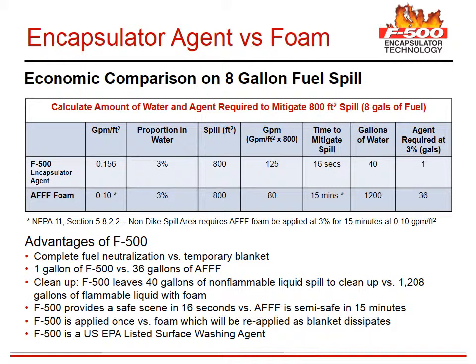At 3%, the foam will use 1,200 gallons of water. The F500 will only use 40 gallons of water. Per NFPA 11, there will be 36 gallons of foam used compared to only 1 gallon of F500.